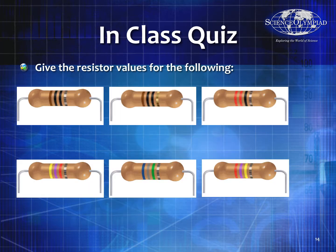Now, in a class quiz, let's look at the resistor values for the following. You'll notice that some of these, like the ones on the top row on the left hand side, are brown, black, black, and the other one's brown, black, black. So the resistor amounts should be exactly the same, but you'll also notice that one has a silver, one has a gold, so they have different tolerances. The rest of them, I think, all have silver tolerances. But even when they use the same colors, if the colors are in different orders, remember it's an order of magnitude problem, so they will be different.